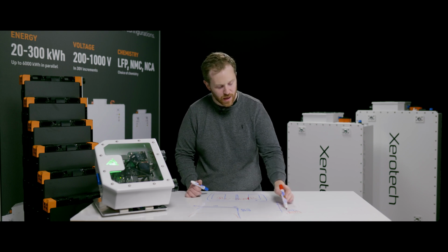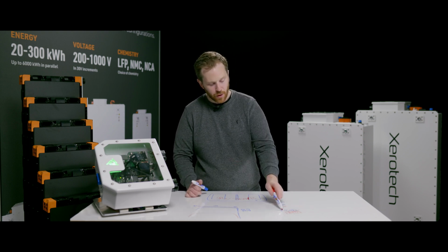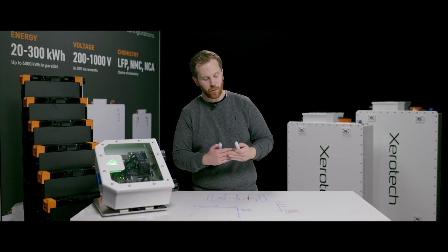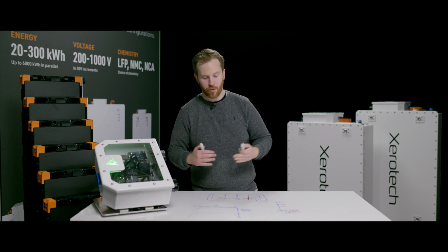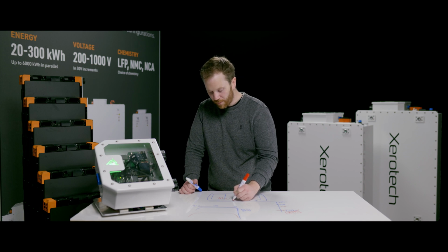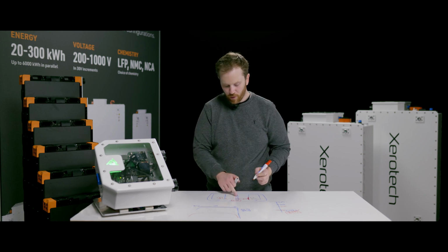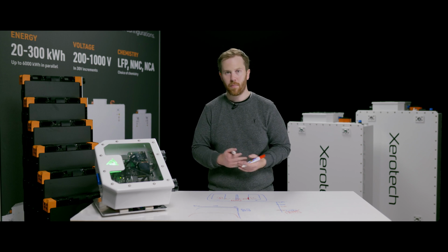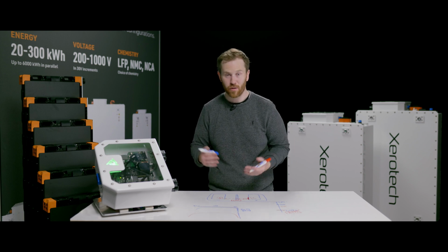But the danger with high temperatures is that there's a certain temperature that becomes close to a thermal runaway condition, where the battery gets so hot that you run the risk of melting this separator, which is basically a piece of plastic that melts at a few hundred degrees, or 100, 150. It causes a direct internal short of the battery, self-heating, self-thermal runaway, heat generation, causes fire. But batteries can and do operate well at high temperatures.